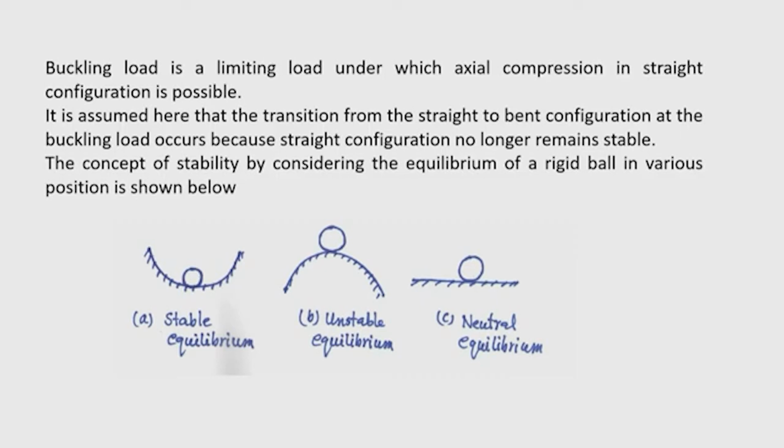Suppose, for example, the plate girder which has the flange and vertical web. In that case the vertical web will buckle like a compression member. So, any steel structure, if you see, is composed of plates. Therefore, plate buckling is important for the design of steel structures.